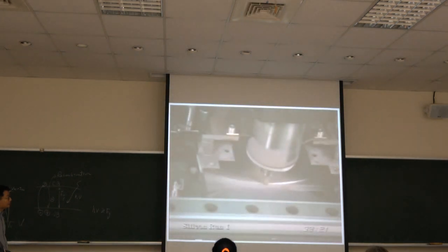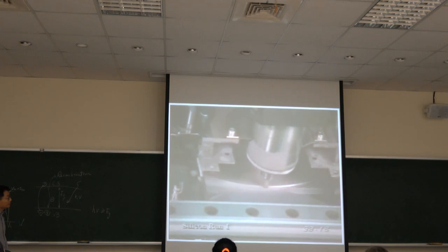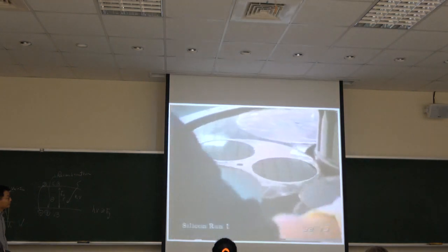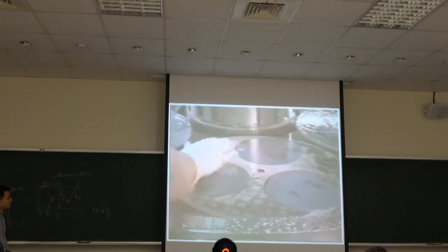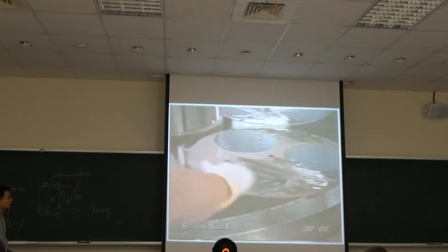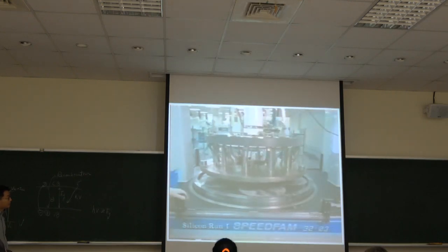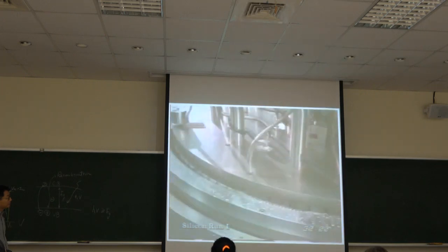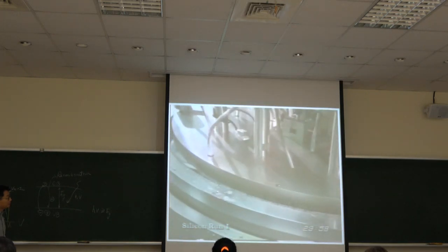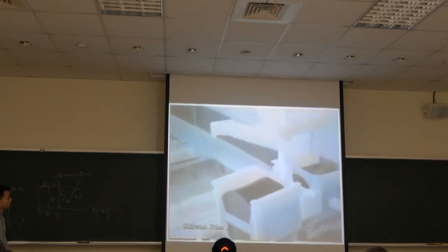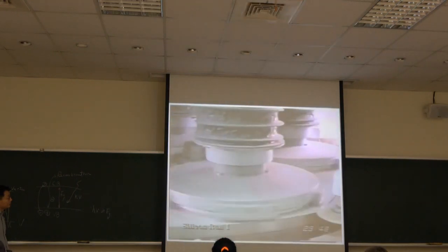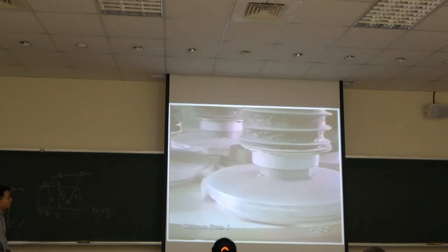The wafers are scrubbed and the edges are rounded off and beveled to reduce chipping. The wafers are then ground smooth on both sides to obtain a consistent flatness and thickness from wafer to wafer. They are rinsed and etched in chemicals to remove surface contamination. The final polish is done on only one side of the wafer.